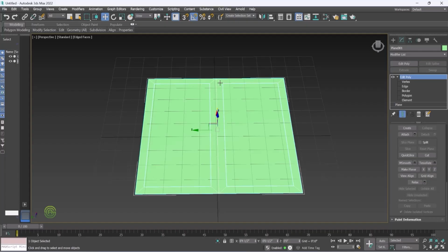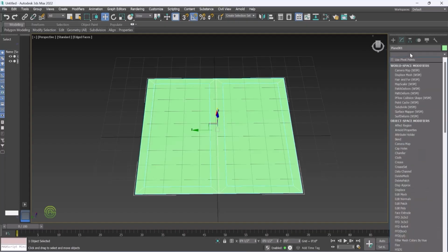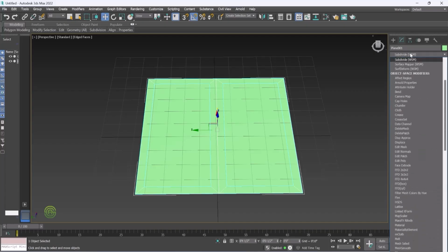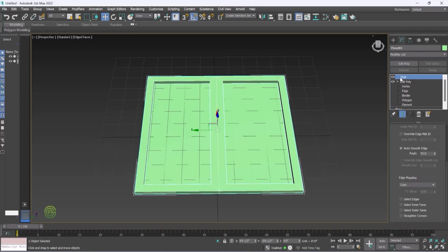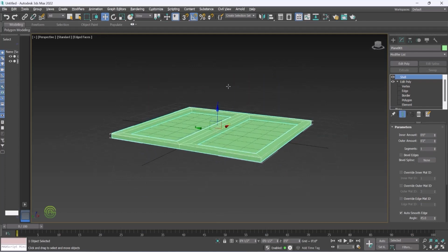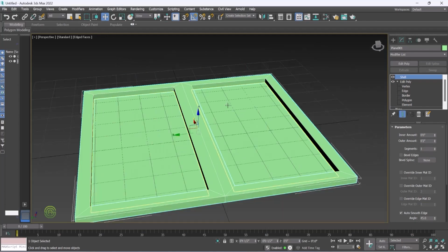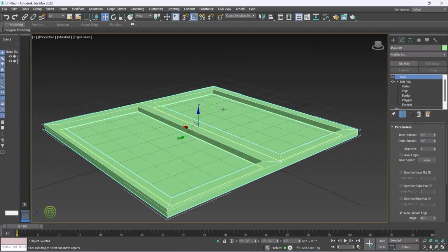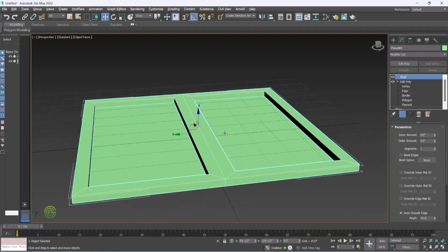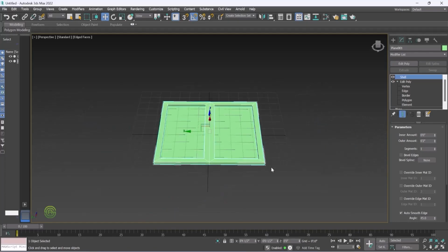So just click on this frame, edit poly, and go to the modifier layer. Just press on shell to give a thickness. Press yes. Now give shell. See, we have 2 inch thickness. Now see, like this, we can create a window. Very easy. This thing is a glass material. This thing is a frame. Like this, very easily we can create a window.